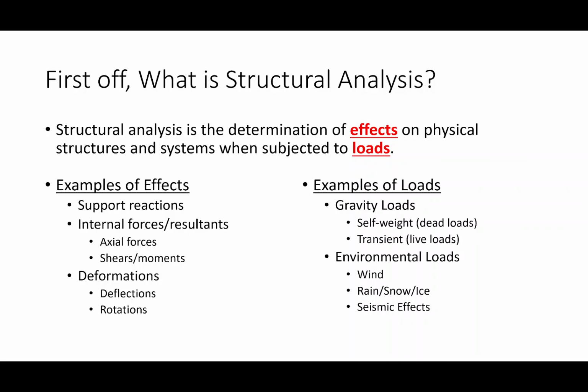There's no earthquake monster pushing on a building, but whenever the ground moves in an earthquake event, we apply an acceleration to a building, right? The building itself has a mass. Force equals mass times acceleration, and so you can get equivalent forces in a structure based on the fact that the ground is accelerating and the building is moving under that acceleration. So designing a structure to resist that is a thing in and of itself, okay?